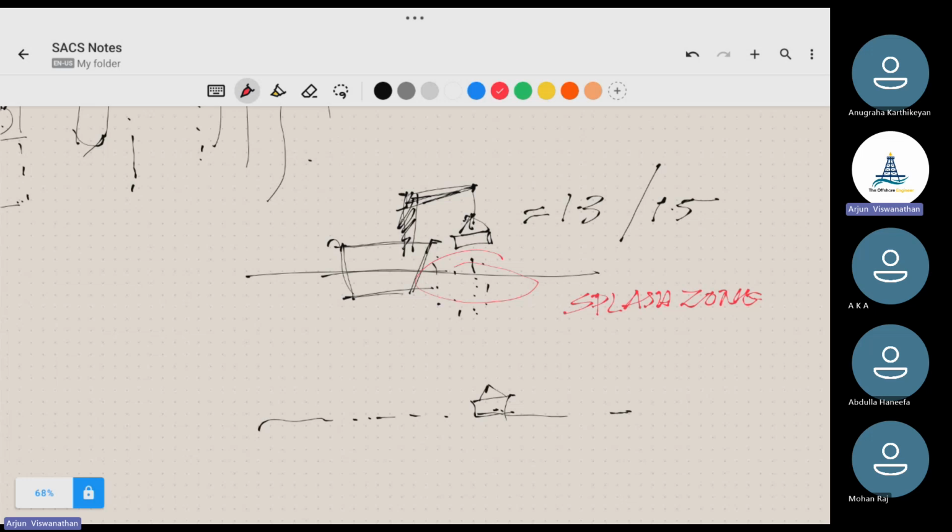This is a very critical part. It will be inducing a lot of movement on the structure. So at this point, the splash zone value, the DAF value, the installation engineering teams used to take it as 1.9, but in my company, structural engineering teams will directly take a conservative DAF value of 2.2. Again, you can refer to the client specs for what DAF they are preferring in this area, but this is the average we take for this particular region.